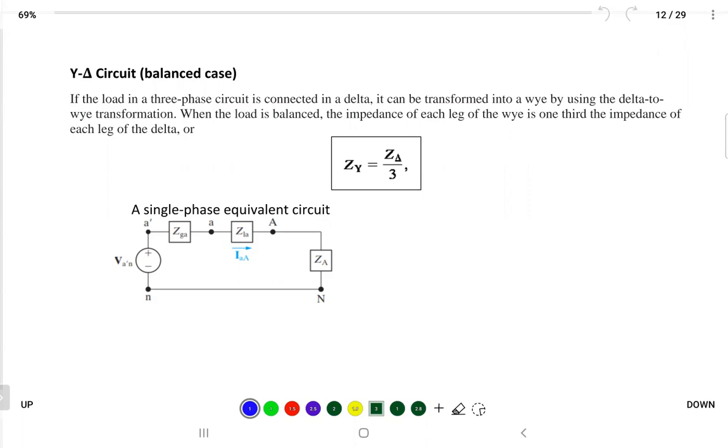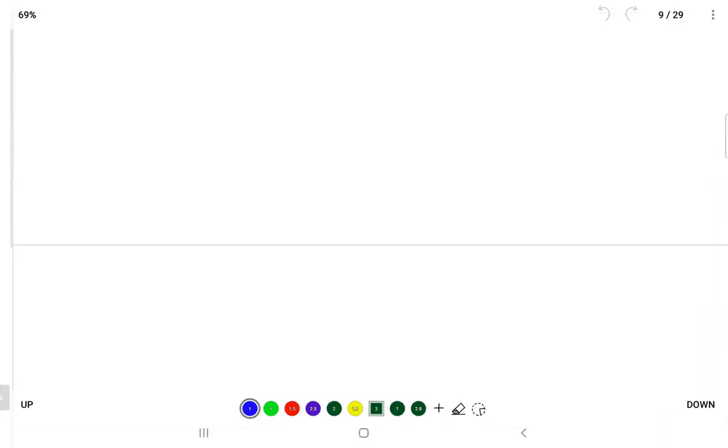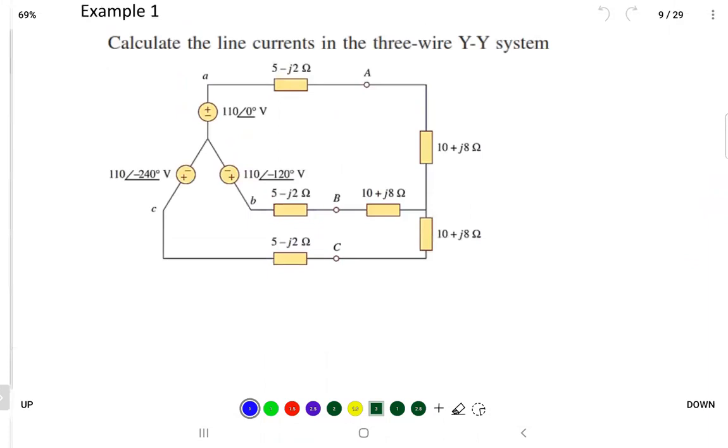Good afternoon, everybody. Last time we stopped after solving a problem of three-phase Y source, Y load. We found out that it's really easy to solve using the single-phase equivalent circuit, just one line, because both are Y. What happens if you have one side not Y connected, not star connected, but delta? Very simple. There are many ways to solve it, but just choose the simplest way.